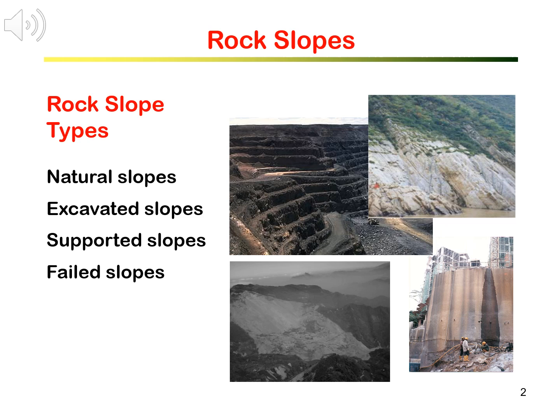The supports for this slope were rock bolts, wire mesh, and sprayed concrete. Please take a look at the drainage holes on the lower part of the slope face. Drainages were provided to reduce the water pressure behind the slope. Because of the high-rise residential buildings on the toe of the slope, on the top of the slope, the loading from the buildings must be considered in terms of slope stability analysis.